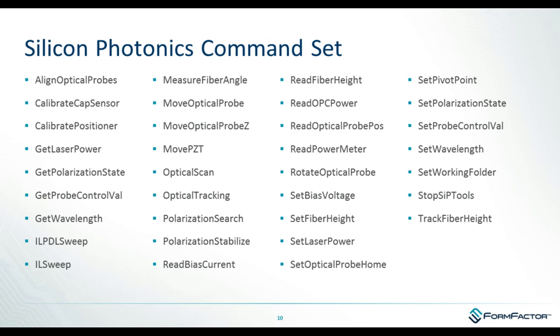This slide shows the silicon photonics command set. For people that may be familiar with test execs and programming probers, in addition to the standard Velox probe commands such as align wafer, step next die, move probe, things like that, the SiP tools add a new set of commands that are available for test exec programmers to script as needed for their motion sequence or their test sequence. I'm not going to go into details on what all these do, but it should give you a sense of the commands available based on what they're called, that you can assemble as you need to perform your measurements.